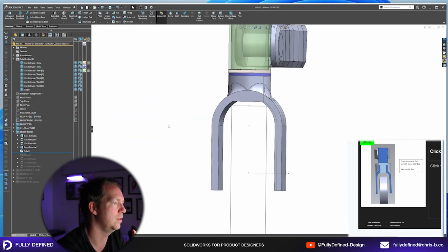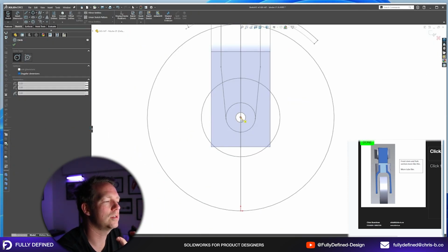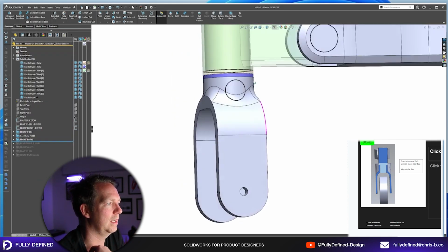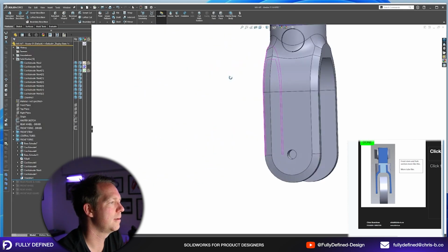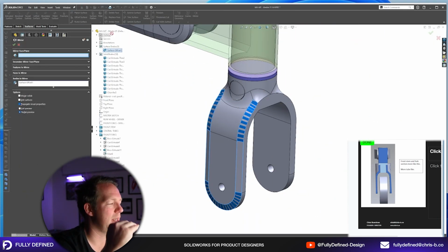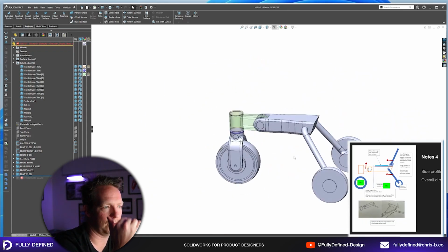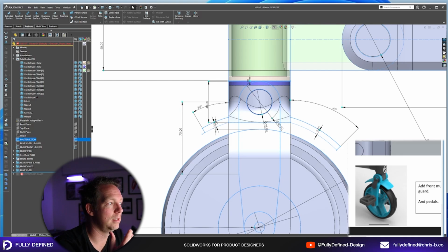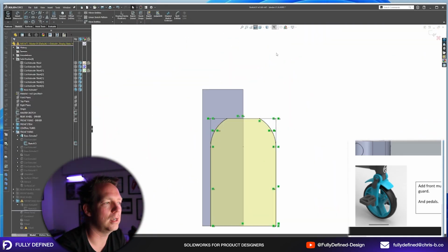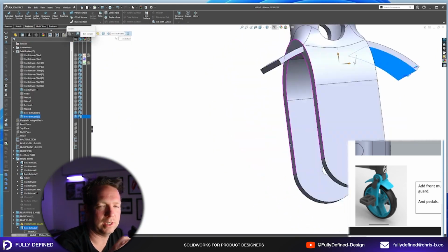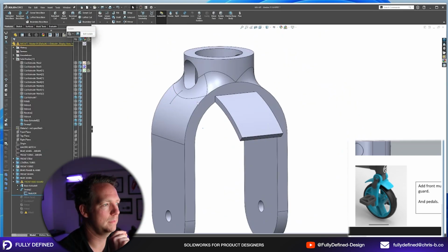The way I like to work through those is top down. So I'll roll all the way back up to the top. I'll change my sketches to reflect my updated design intent, or the updated design intent of the client. I'll make those changes, and then I can roll down, and any errors that pop up, I'm knocking them off one by one from the top to the bottom. And sometimes you might resolve the design of that feature, and then any features below that are actually now obsolete. So even though there are errors there, you can just select them all and delete them.